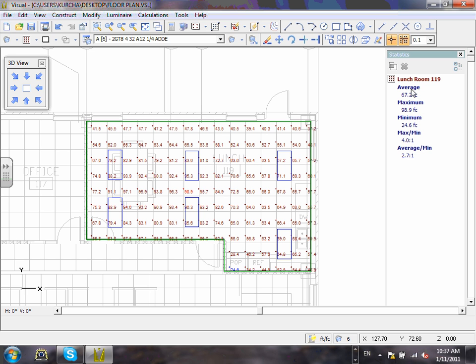Here's what you can go play: you can put 3 lamps. In your ideal application, guys, when you do lighting, you really don't want to go lower than 3 lamps because there are too many fixtures. So 3 lamps are best. If you can do your design with 3 lamps, that's kind of the optimum design between how many fixtures and good distribution. Okay, I can't emphasize this enough.